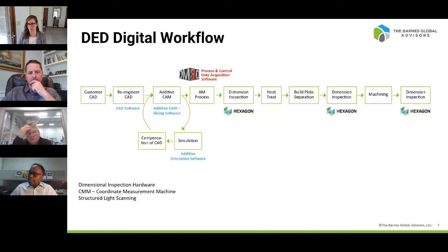In the development cycle, typically metal AM goes through several iterations before you get the part right. And that's where I think simulation comes in, and Jeff can talk about it better, how we could use these tools to integrate with the process development and cut down the iterations needed during the printing process. That will cut down time as well as cost.